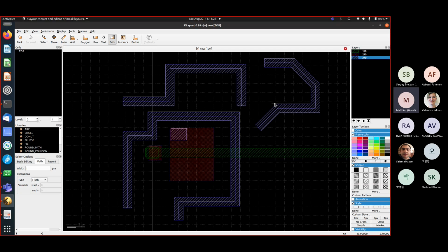So typically in technologies like maybe Skywater, I'm not sure, but more advanced nodes, you never can do 45-degree angles. You only can do rectangular or horizontal, vertical only Manhattan structures.